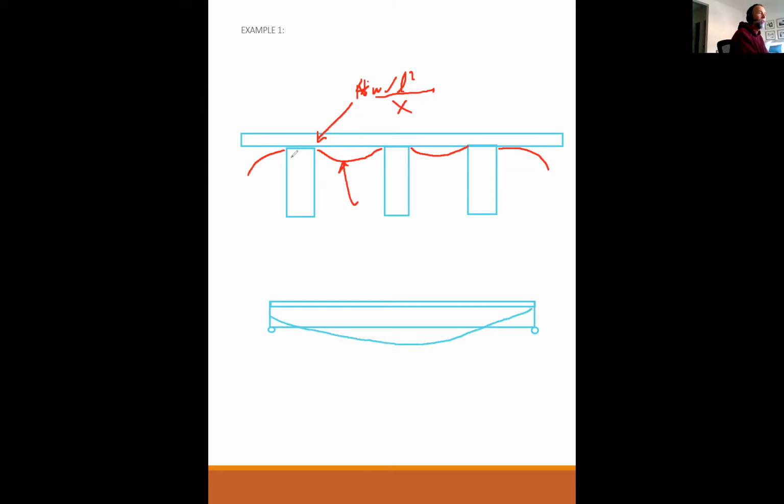So you see, what the slab is trying to do really has nothing to do with what the beam's trying to do. They're totally two independent systems. If I put a big load right here, I could fail the slab. This could fail through and fall through. The beams are fine, but I could fail that slab.